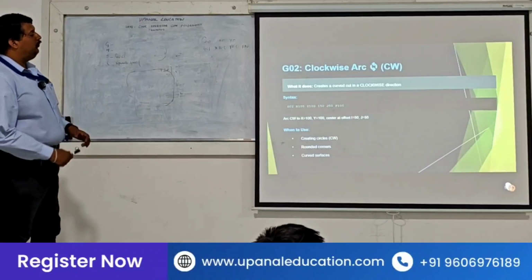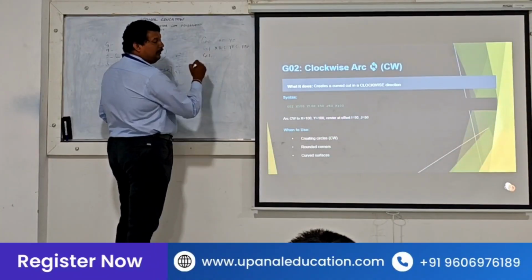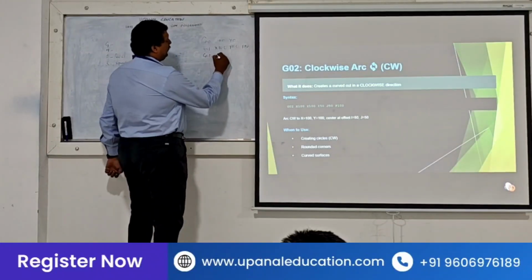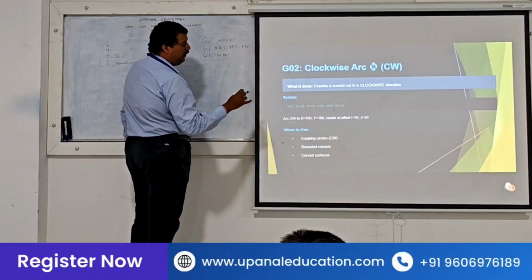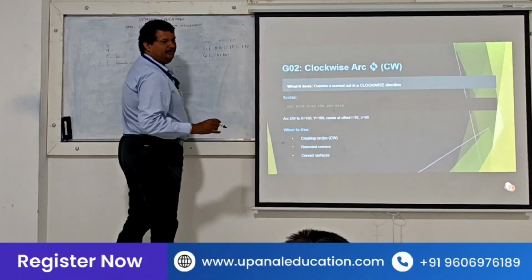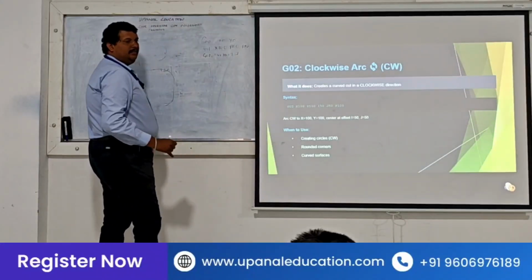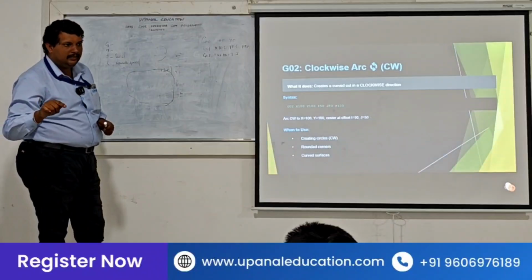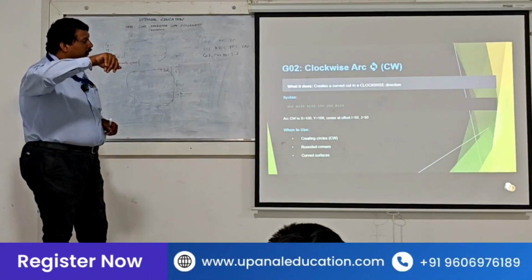Now here, when we put the program G02, two more letters will come. As usual, X100, Y100, that's normal. But we will have I and J. I and J mean that there is a radius there.